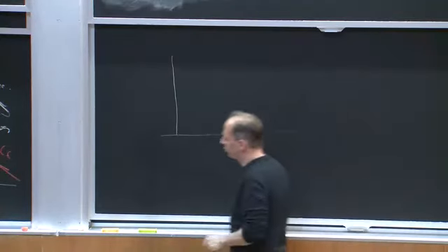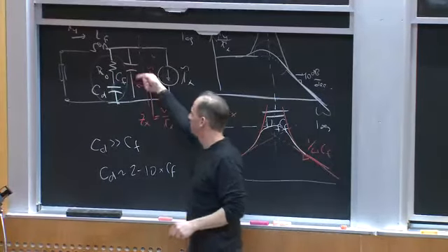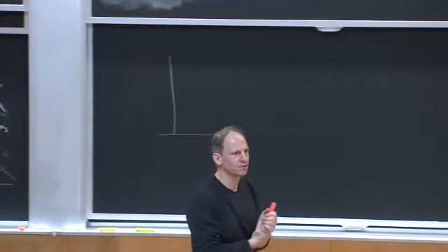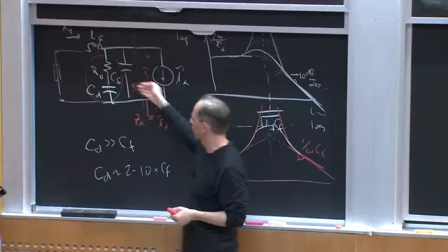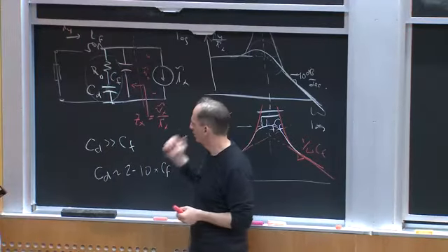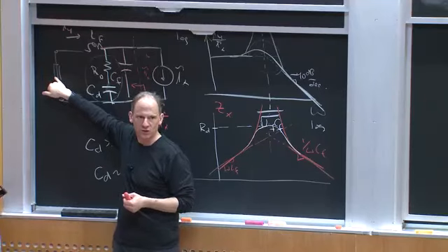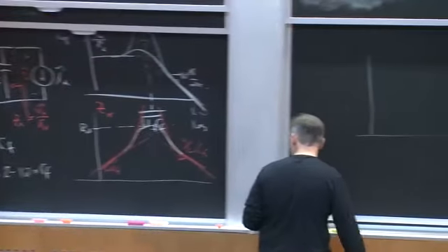I'm going to look at ZX, the filter output impedance, and we're going to come back to why I'm obsessed with what the filter output impedance looks like. That's the impedance seen looking back, what the converter looks back and sees. In my analysis here, I'm just assuming that the source impedance out here looks like a short circuit. I'm making that simplifying assumption.